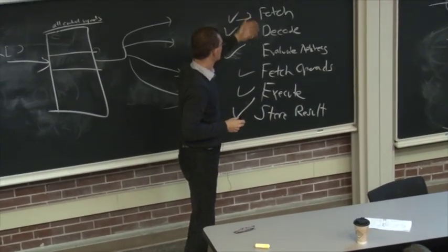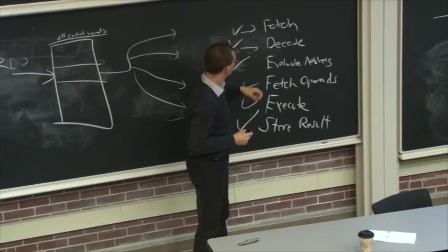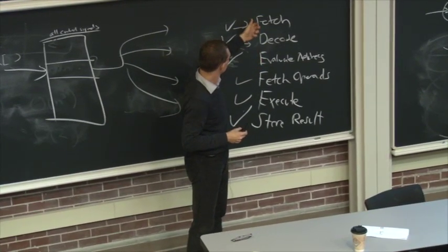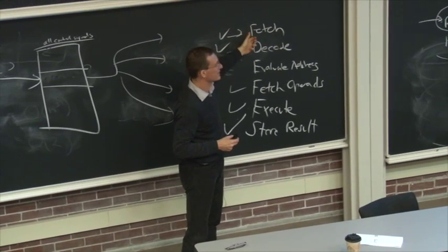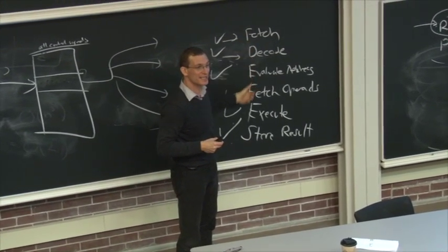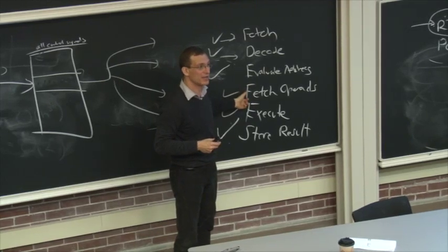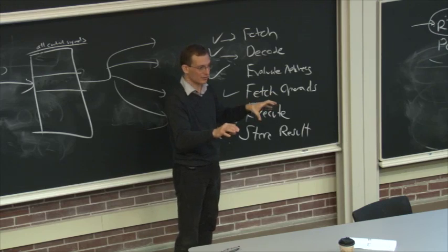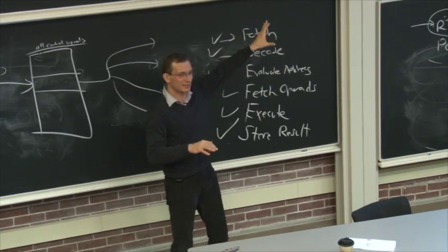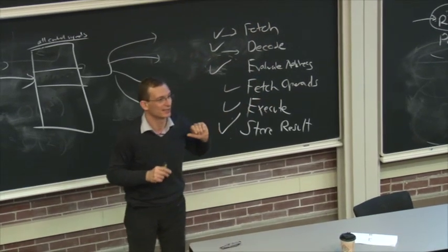Well, which instructions do two adds? For example, if you're incrementing the program counter as well as adding registers, right? If you had multiple cycles to do this, you could use the same adder to do both. Now, we didn't do that because it's a single cycle microarchitecture.